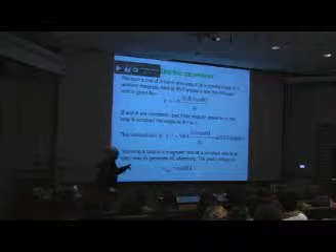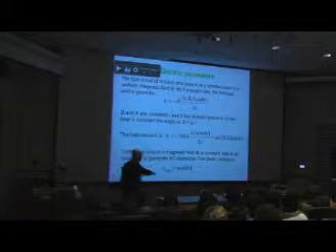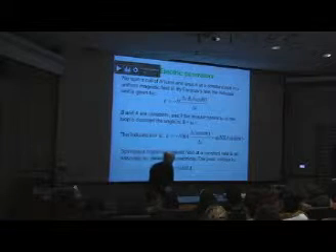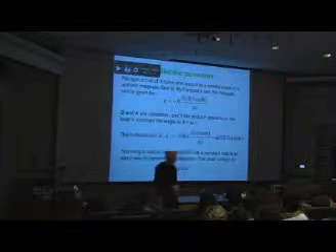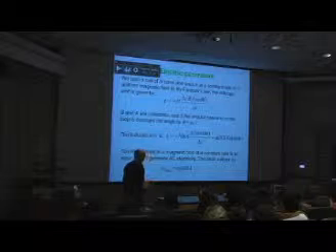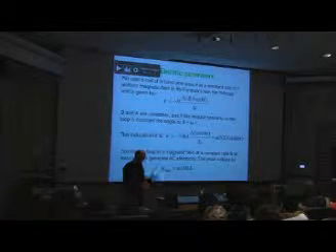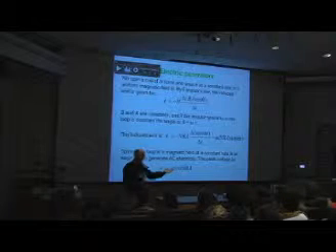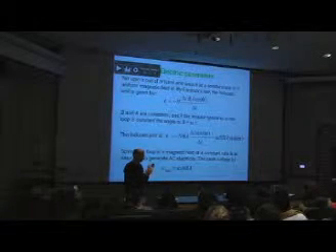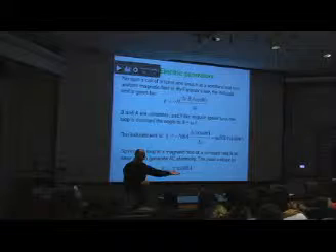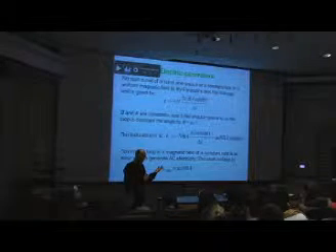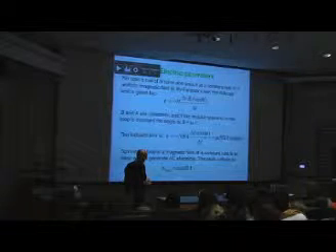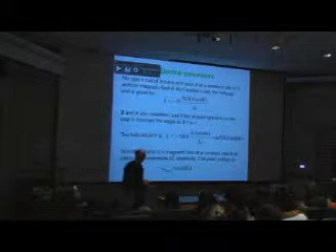Okay, any other questions on the pre-session quiz or this equation or anything? There's one. How do you do the RPM calculation? Okay, so you're okay with getting omega in radians per second? Okay, so then you just got to convert from radians per second to revolutions per minute. So there's two conversions there. One is to go from seconds to minutes. That's a factor of 60, right? Not 3,600. I think some people actually make that mistake, but it's just 60. We're not going all the way to hours, just to minutes.